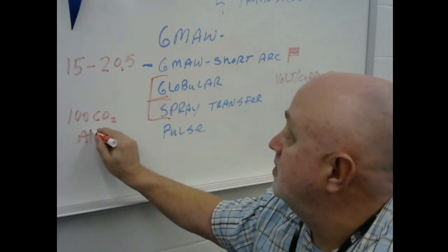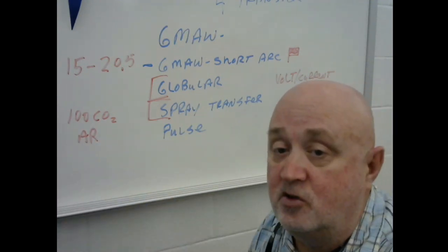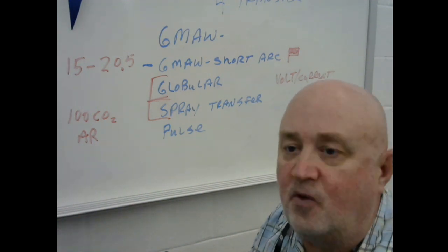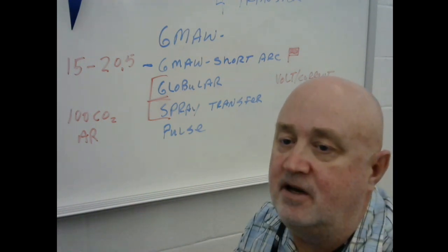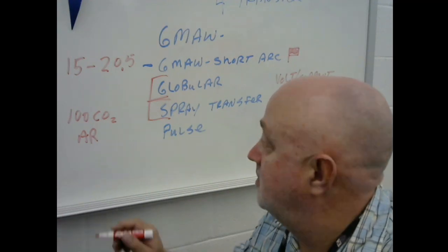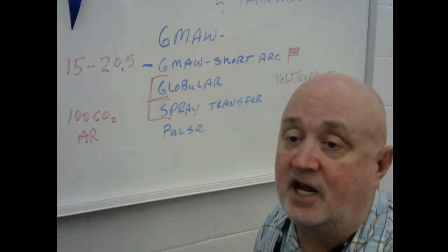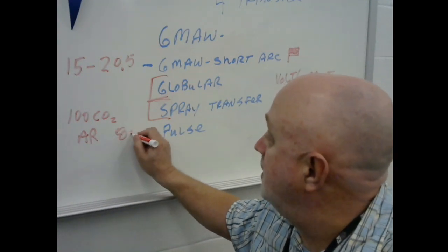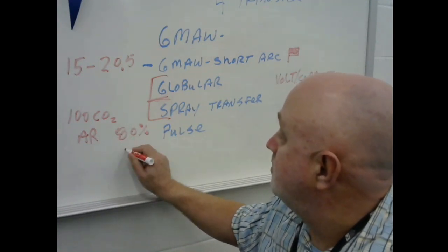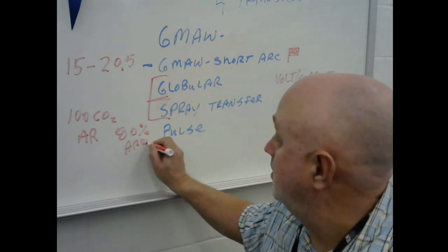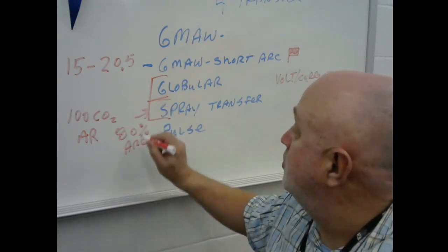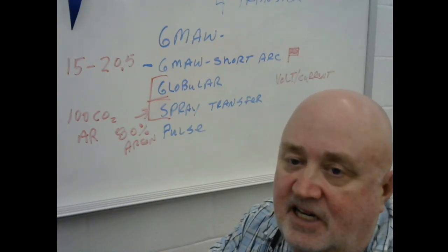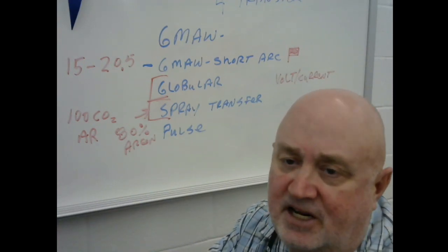Argon will. But to do that, and once again, if you're an expert at this, I don't want to argue with you, but 75-25 will not get you into the spray transfer mode. You need at least 80% argon for spray transfer to work, minimum. Some people say 78, maybe it's 82, but I shoot for about 80.